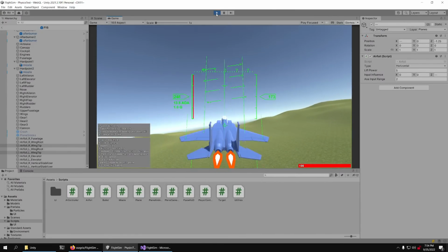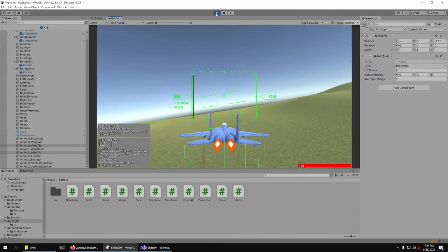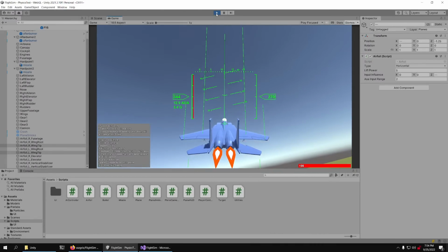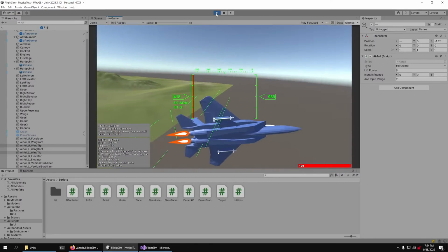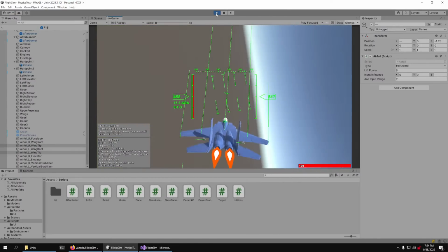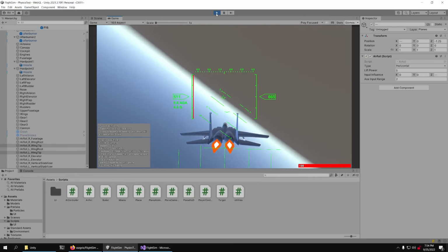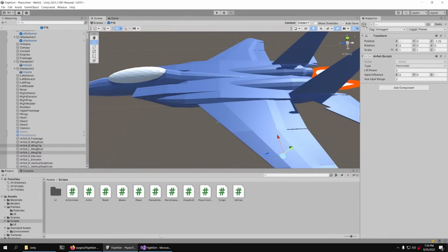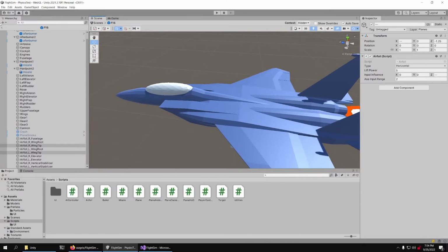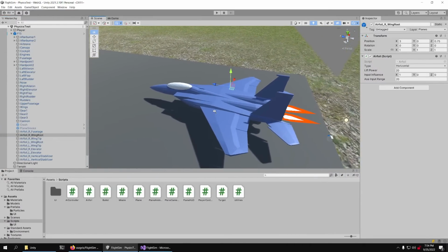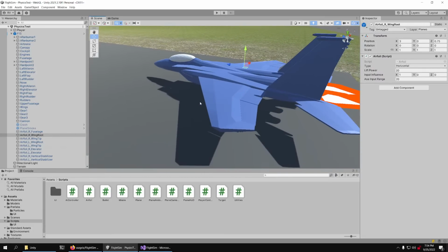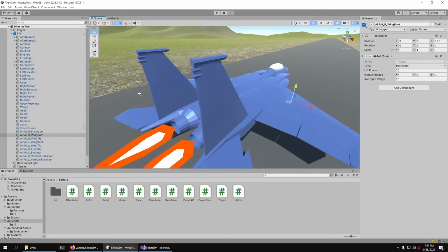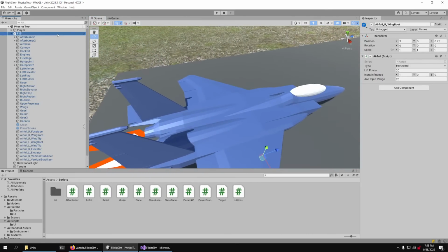So we can see, even when I'm not actually giving stick input, when I hold it like this and then release it, the nose just oscillates up and down, which is way too strong of stability. It wants to keep the plane aligned with its own velocity, and I need to figure out some way to break that so we can actually control it. This is a problem real fighter jets have: they need to be unstable so you can actually turn them quickly. Passenger airliners generally want to be stable, but fighter jets need to be unstable. So I need to figure out a way to reduce stability.